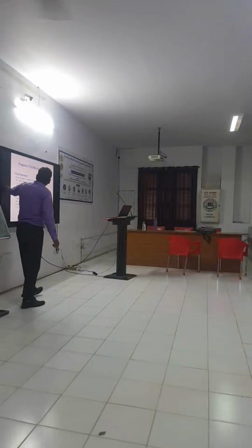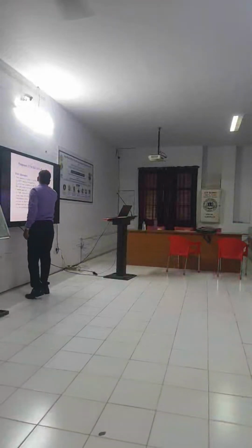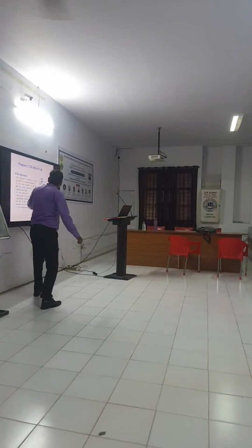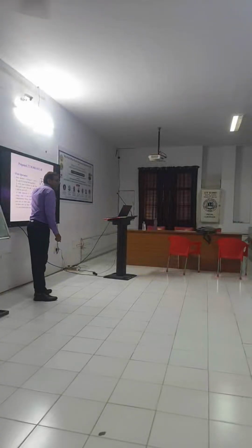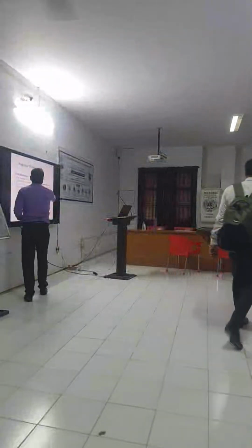The write operation is initiated by turning WL and WLB on. How can we make this one on? Here apply a rising pulse or high. WL is 1, WLB is 1. No, sorry, 0, because the gate of the PMOS should be low, then it will be on. So 0 or high, then it will be on. Getting it?